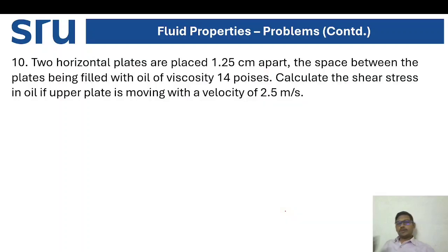Now we will see another problem. Two horizontal plates are placed 1.25 centimeters apart. The space between the plates is filled with oil of viscosity 14 poise. Calculate the shear stress in oil if the upper plate is moving with a velocity of 2.5 meters per second.